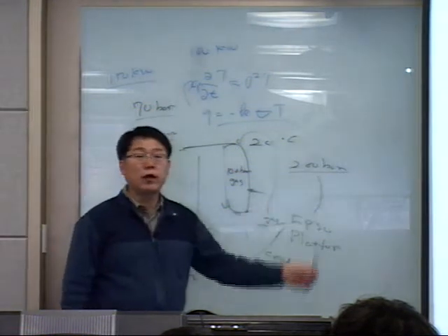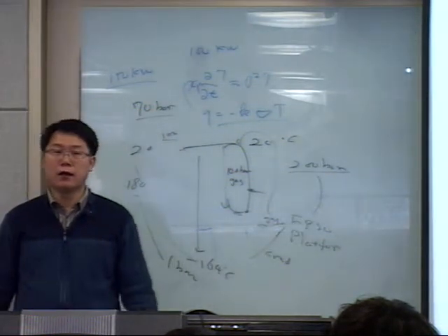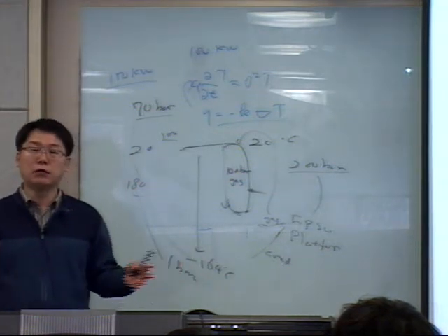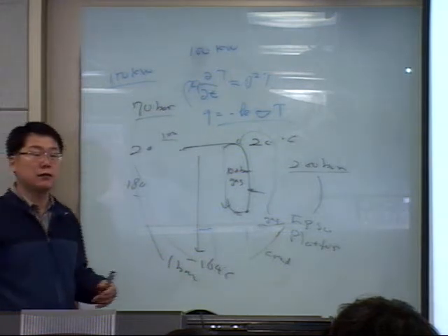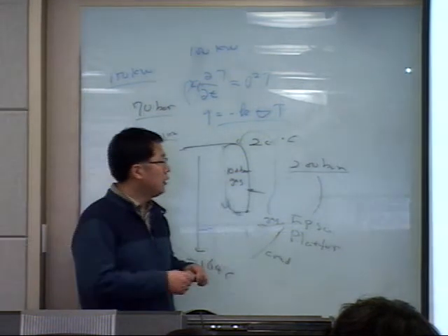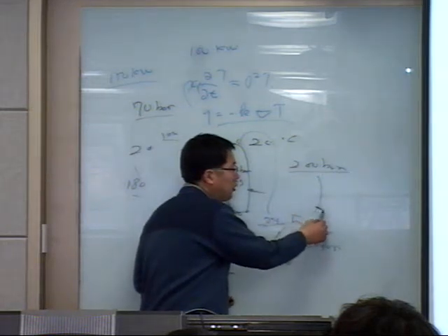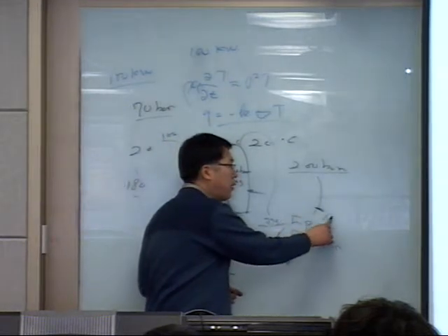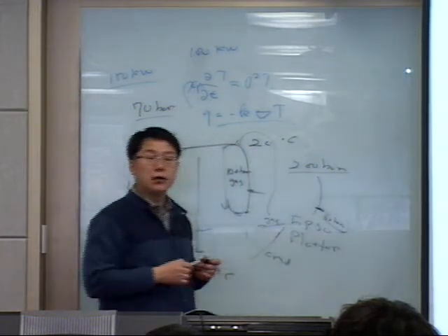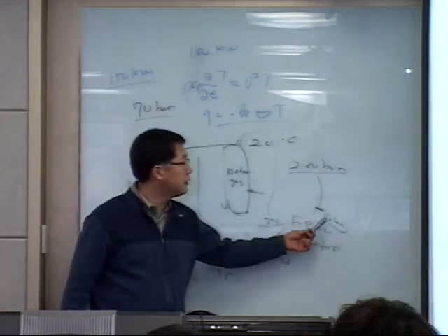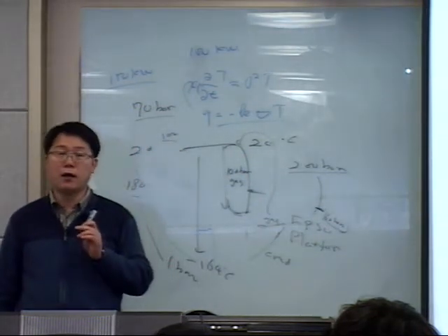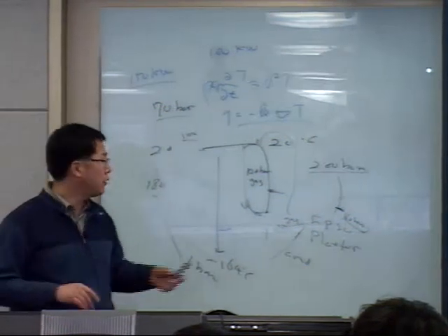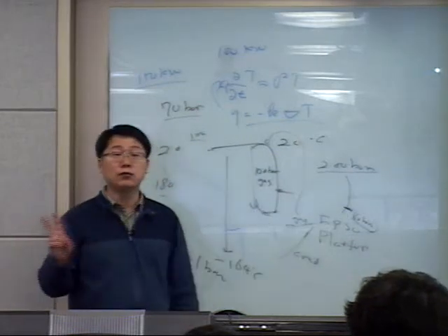Usually the pressure 200 bar is too high. I mean the piping and the equipment to design this high pressure system is difficult. So usually before it reaches the LNG FPSO processing plant, the pressure is decreased to 60 bar. So what you can do is to compress 60 bar to 100 bar. That kind of compression is very simple. The compression ratio is less than 2.